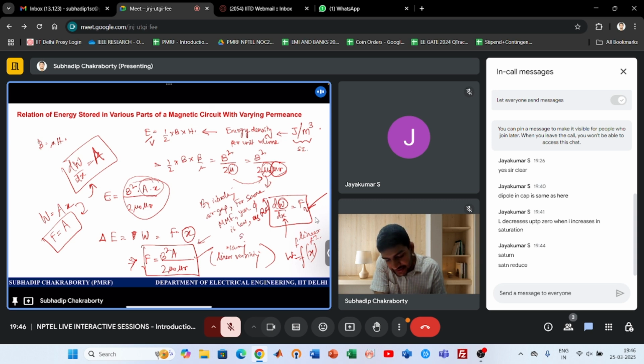Right. So saturation is avoided. For a large value of current also you can avoid saturation. Obviously the coils should also electrically carry that current. But I'm assuming you used correct SWG wires and cross-section areas that can pass that amount of current. So for a high amount of current also your flux is low. For the same MMF, due to the increased reluctance of the core by introducing an air gap, you have now increased your band before saturation because your flux reduced.